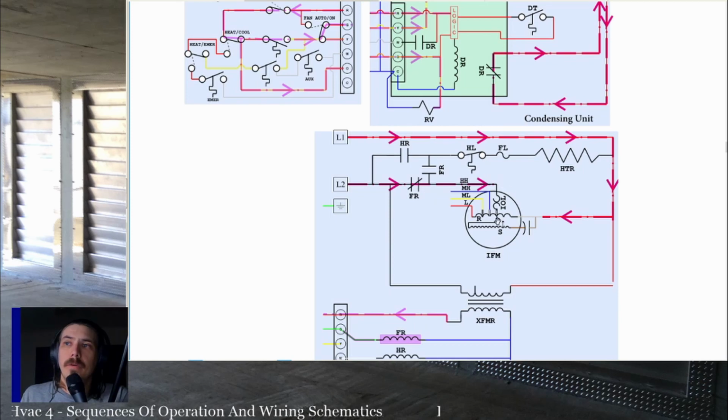That sends power to whatever speed you have selected on your multi-speed blower, if it is multi-speed. Otherwise, it powers your terminal there. L1 is always powering the other side of the indoor fan motor. In this schematic, if you had a double pole set of contacts, that set of contacts would also be closed from the fan relay.